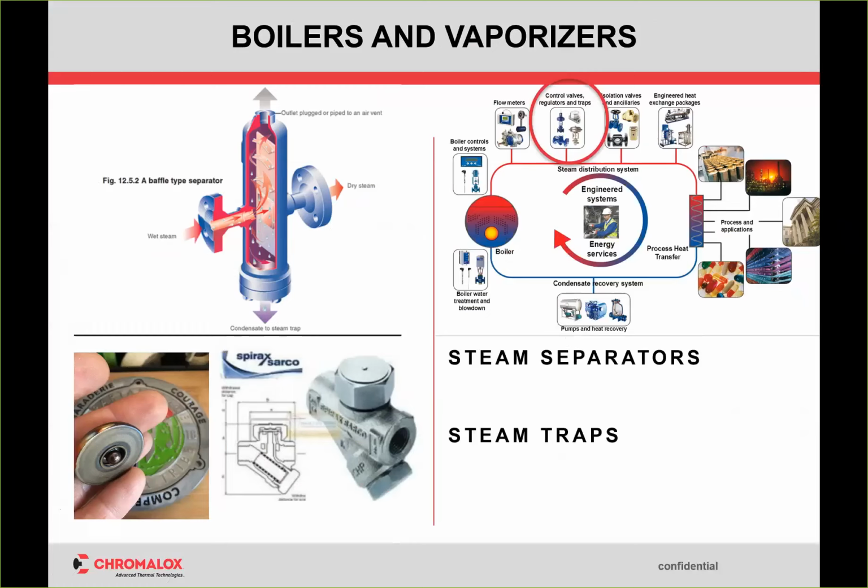And they'll put steam traps along the way to improve the quality of steam. We're getting the moisture out of the steam, and we're letting the steam go, but we're getting what's already condensed out of the way. And that improves the thermal input to whatever process we're providing.